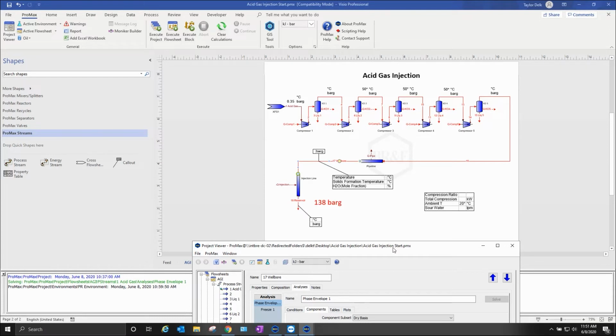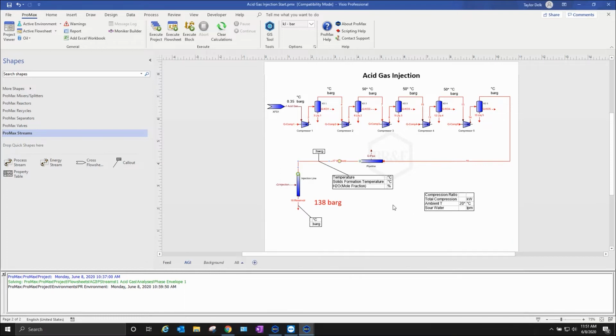That higher density liquid or supercritical fluid is going to be pushing down through the hydrostatic head effect in the wellbore. That's going to give you the pressure increase you want to go down to the reservoir. And so if we can get liquid forming here, it's going to take a little bit of the pressure off the compressor system to compress it up to that reservoir pressure. So the higher density will push down harder, and that'll help us out. All right, so let's go ahead and get simulating.